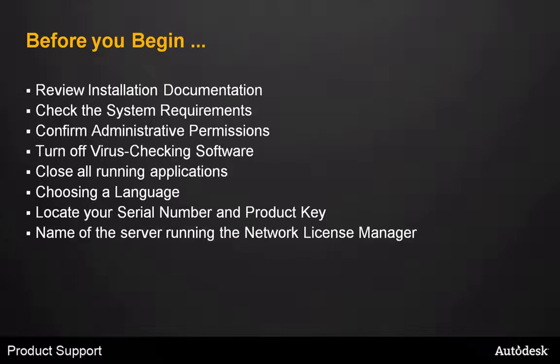Because this is a network installation, you must know the name of the server running the Network License Manager. You can use the command prompt and run ipconfig /all to find that information. In addition, you must choose a licensed server model.